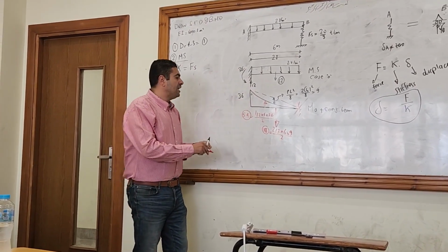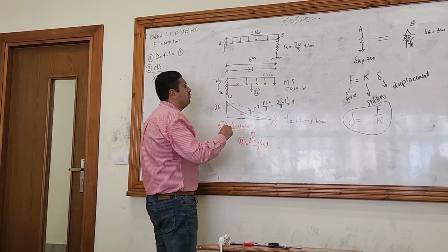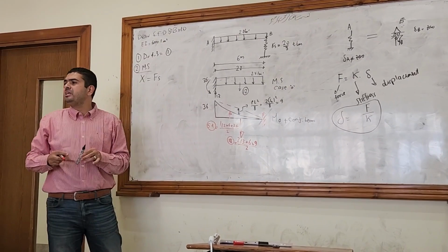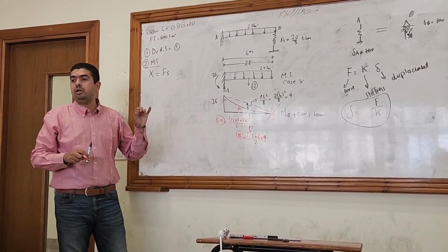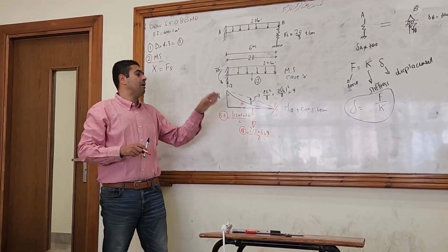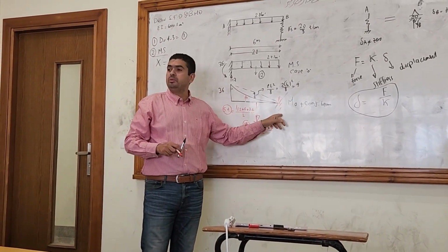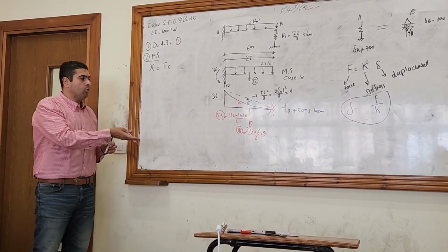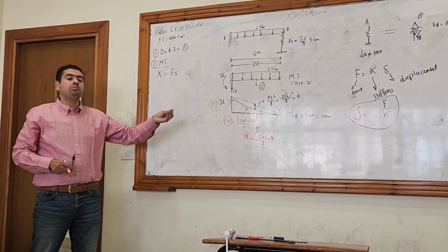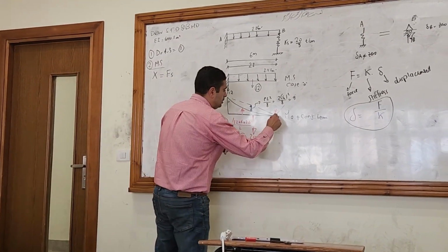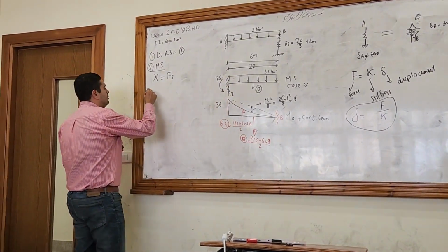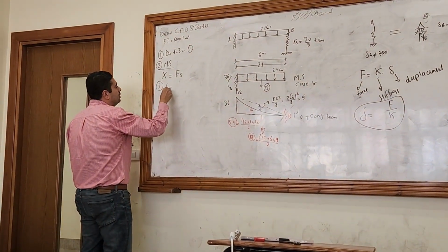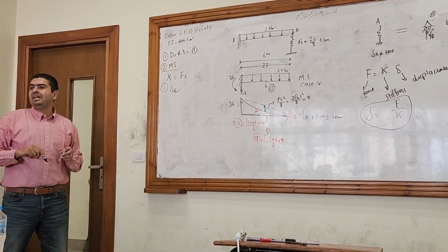But here, I need to calculate the vertical displacement at B. What is the displacement, deflection-wise? It's the bending moment from the conjugate beam at B. So now I need this moment. That's my target now, so that's why I have to calculate the moment at B. So let's call it delta B. I need now to calculate delta B.